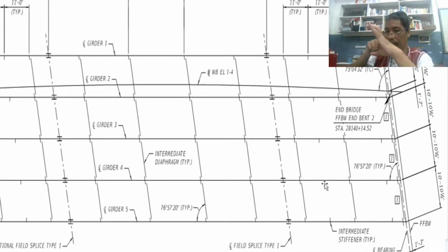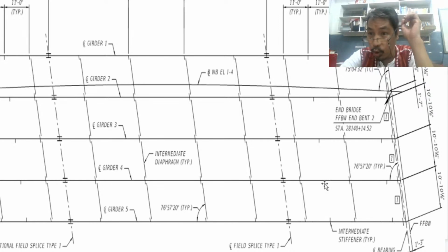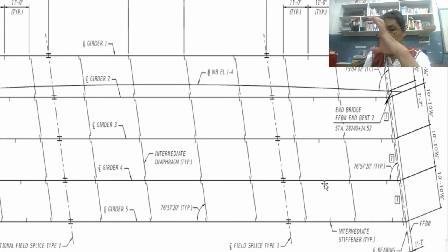So the W-type beam looks like this. A W-type beam looks like a double C channel, di ba? So we can make a flat bar that could be welded like this at exactly this location. So you can weld an intermediate stiffener. The distance of stiffener to stiffener is 22. Another 22 stiffener, another 22 and so on.